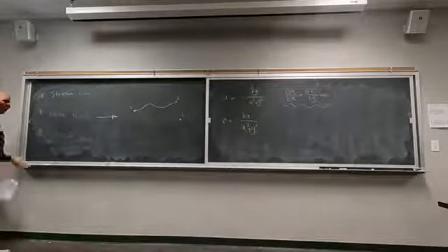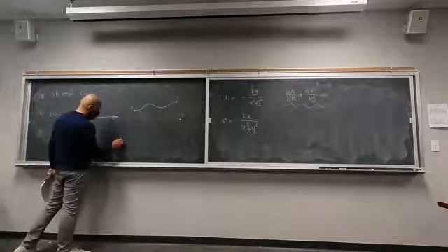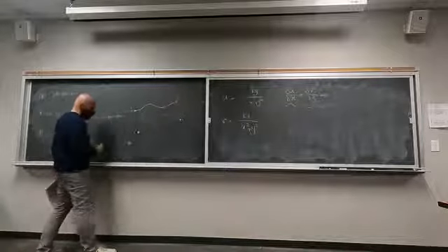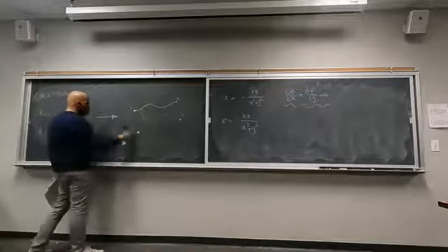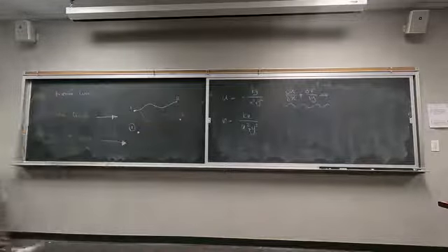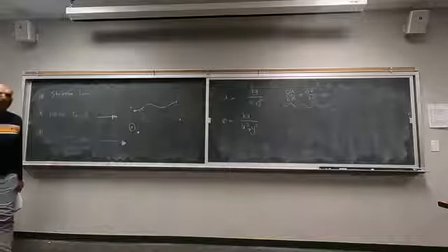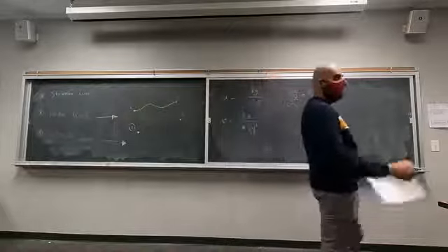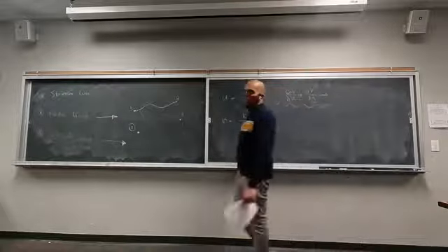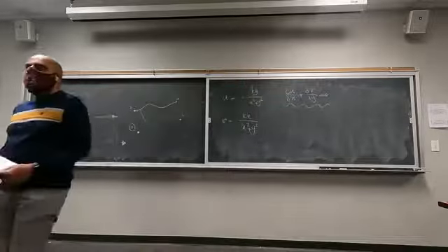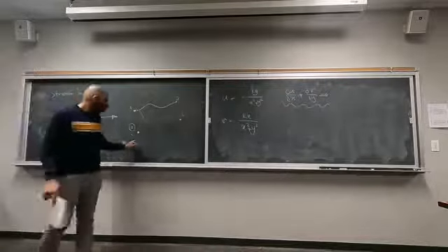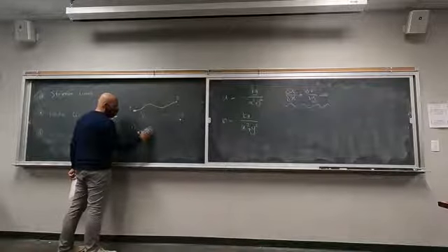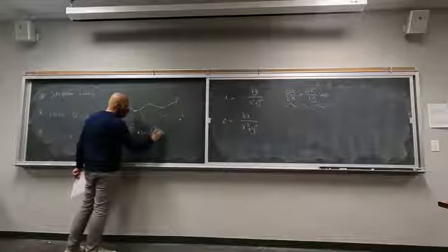A streamline, or let's talk about a streak line first. A streak line is a combination of all of the fluid particles or fluid elements that have passed through point 1 at a time delta t, right, at 1 second. Let's say after 1 second, 100 fluid elements have passed through this point. The location of those after this 100 seconds is going to be your streak line.